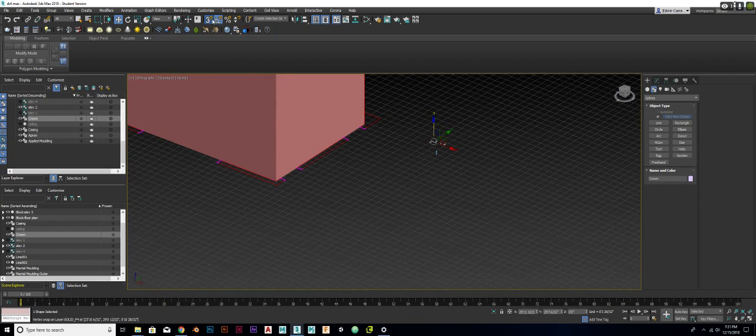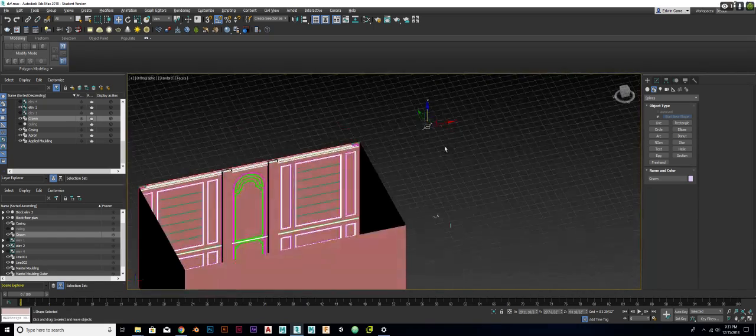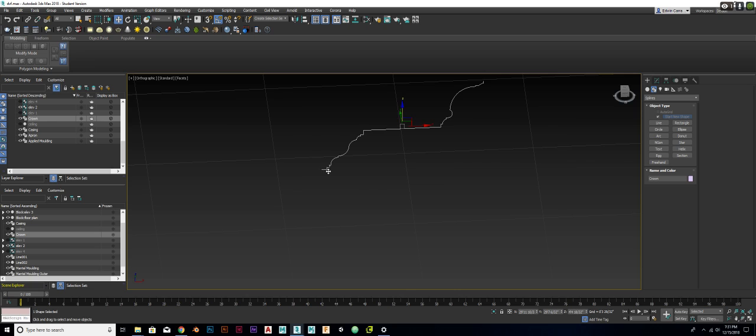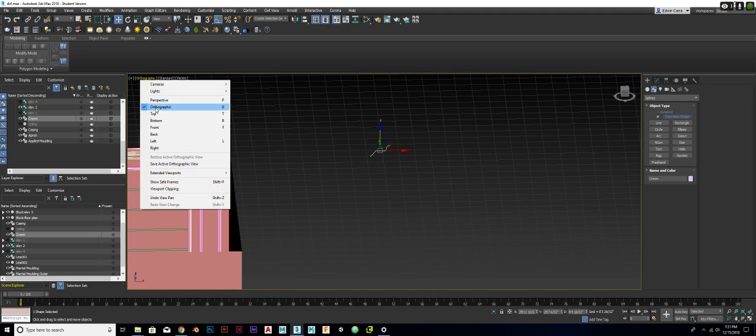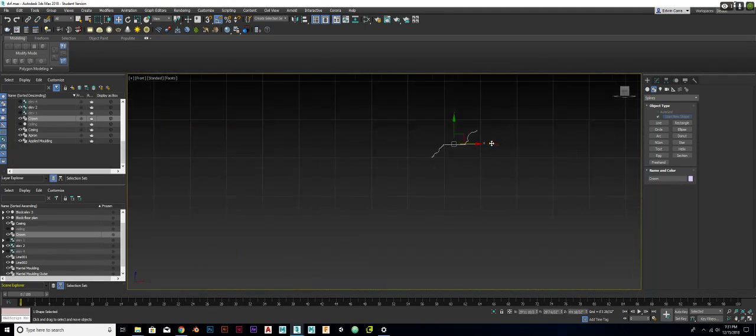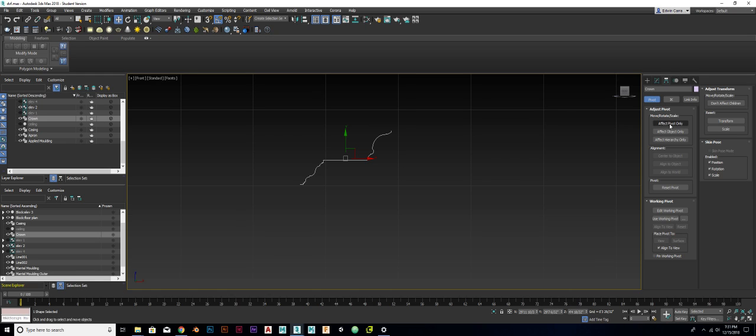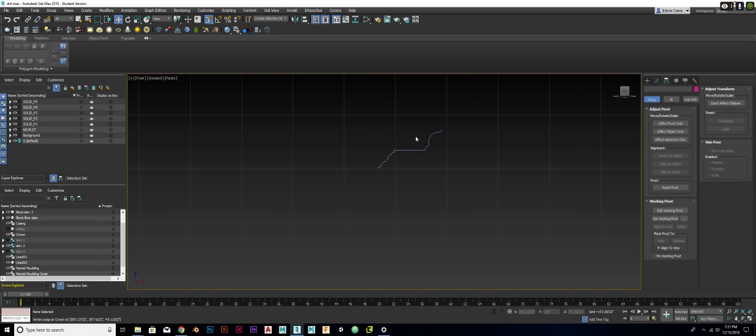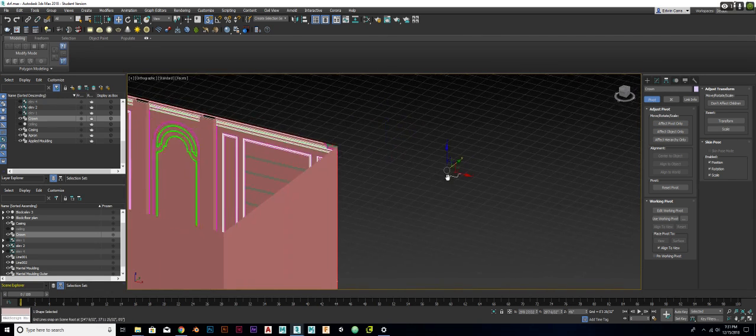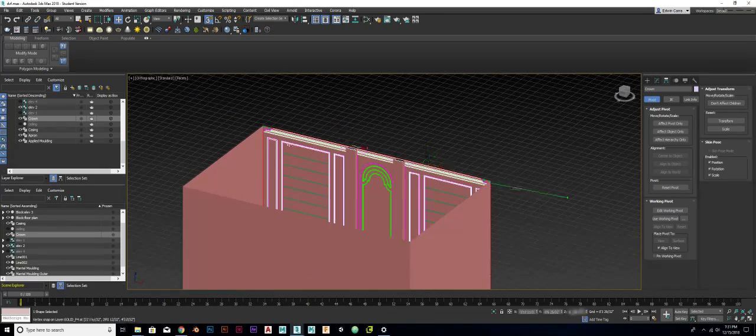Okay. It's snapping. We're gonna change the pivot point on this. I'm thinking the pivot point needs to be, I'll show you guys. Let me go into front view here. I think we want it over here, because that's where the top of the wall really is. So if we affect this pivot point, let's turn snapping off. We'll come up, and then we'll effectively set that pivot point right there. I think that is going to be the best way to make this happen.